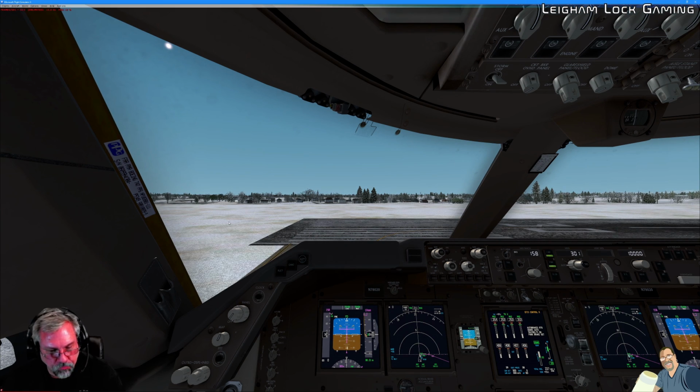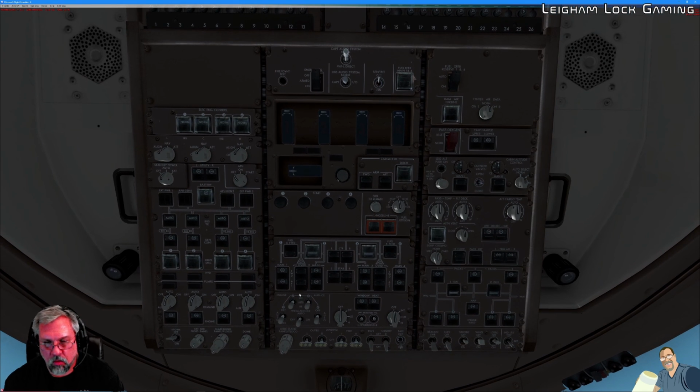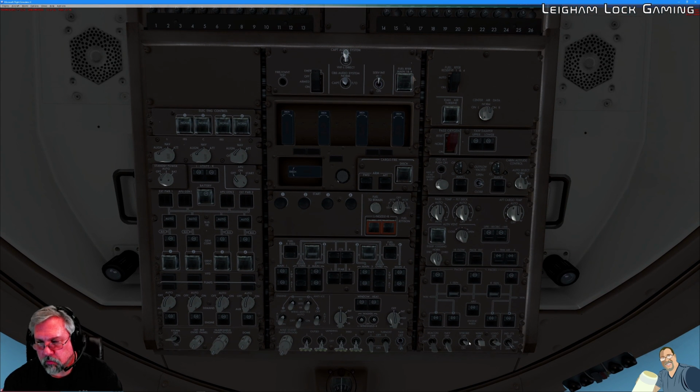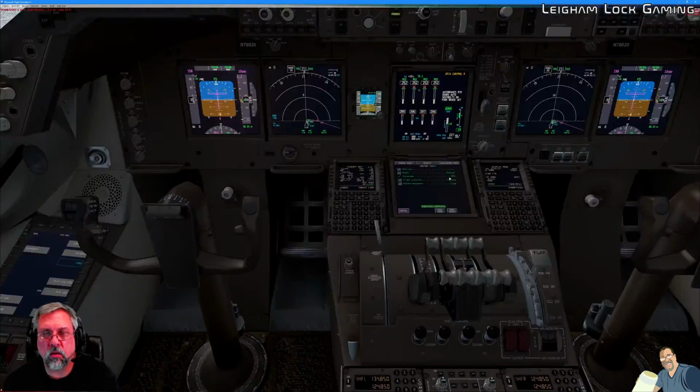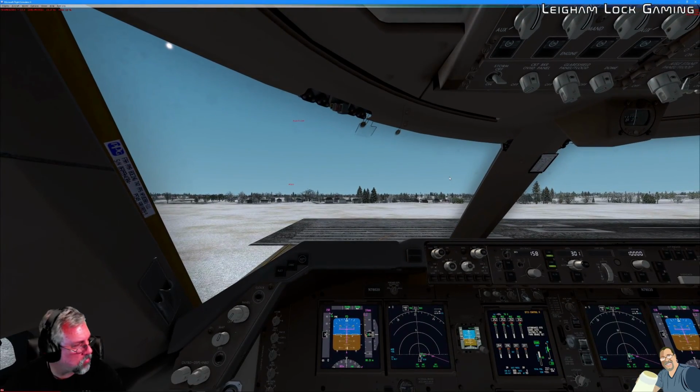Primarily, get our landing lights turned on. Get our strobe light turned on. Get our TCAS system put into TARA. Double check our checklist here real quick.